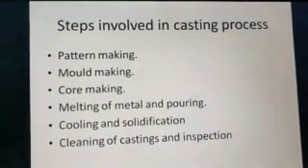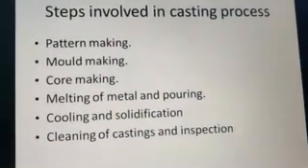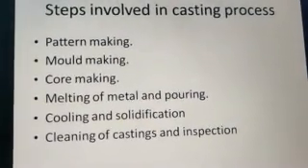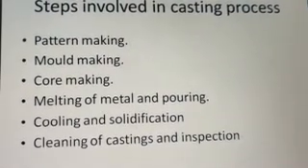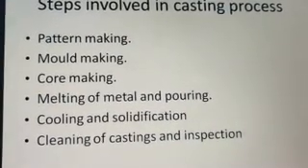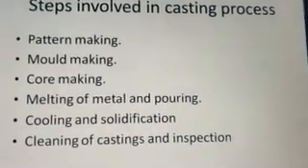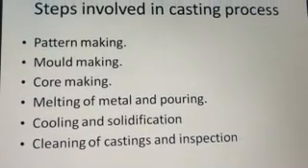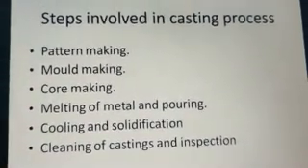So sand casting basically involves all these following steps, starting off with pattern making. Like I said, pattern making is a tedious effort. You need to pay really good attention while making a pattern, because your pattern determines what your mold would be like, and how your mold would be like will determine what your product is. And in case your pattern is lacking the finish or the dimensional accuracy, the entire product line would be affected just because you didn't pay attention in the pattern making. So starting off with the primary step of pattern making, we go all the way till the cleaning and inspection of the castings.